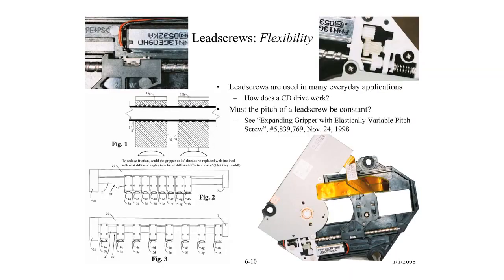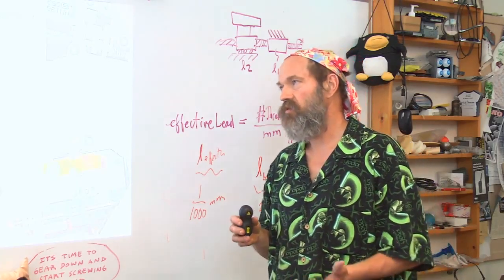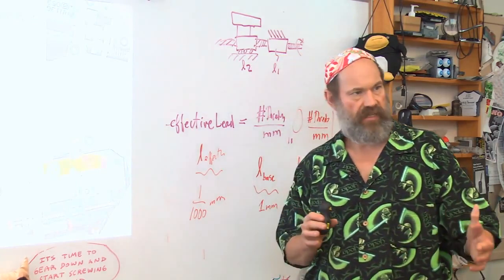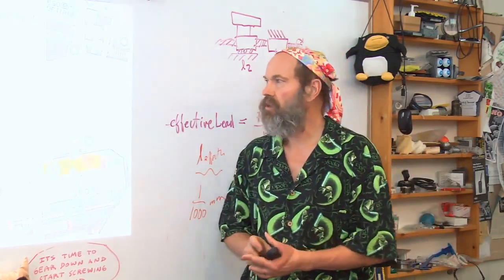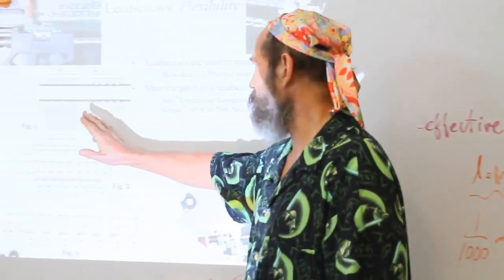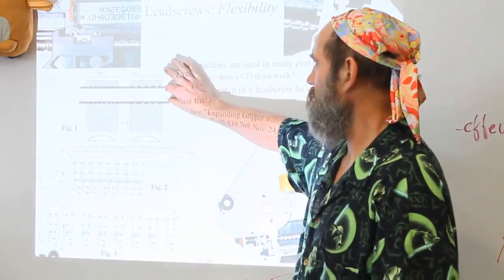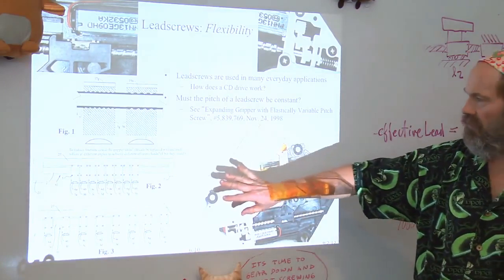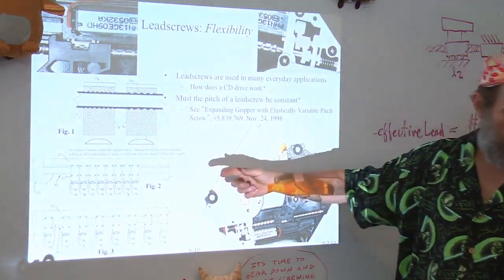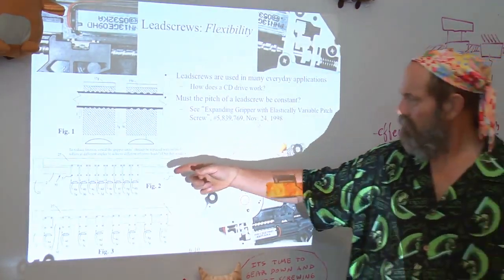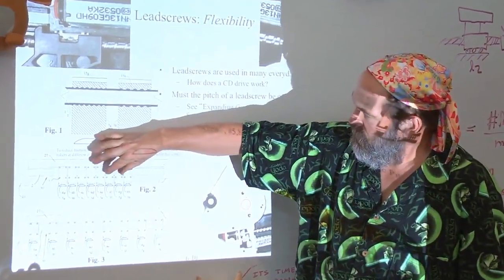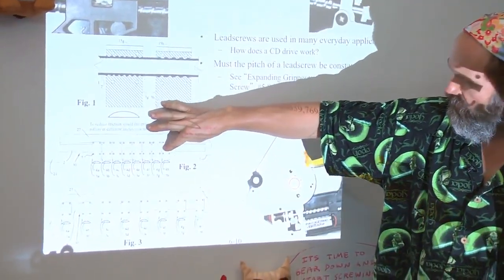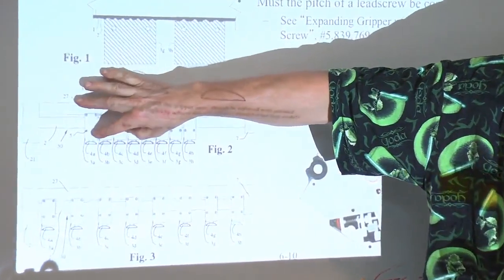The opposite of that is flexibility. Maybe you don't want a really high stiffness machine. Maybe you want some softness or flexibility to accommodate misalignment. You can imagine grippers that are made on rubber lead screws, so you can have differential leads very easily. This was a gripper we did long ago that when you turn the screw shaft, you could have a whole bunch of nuts attached to grippers on it.